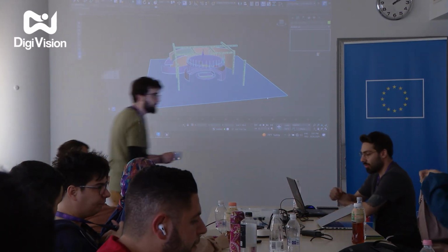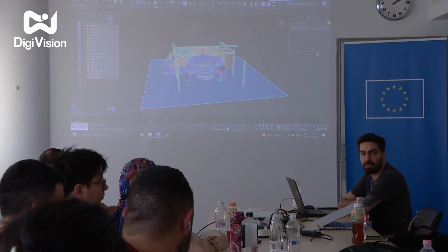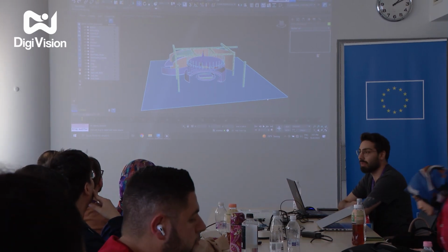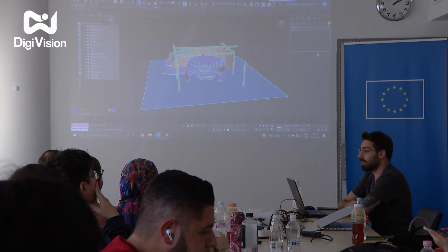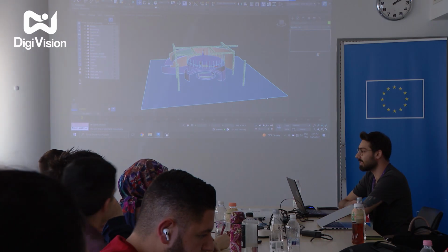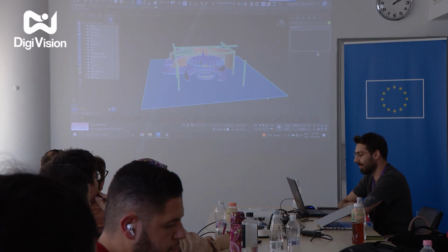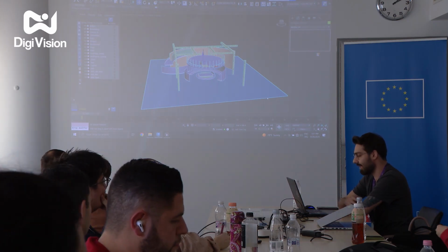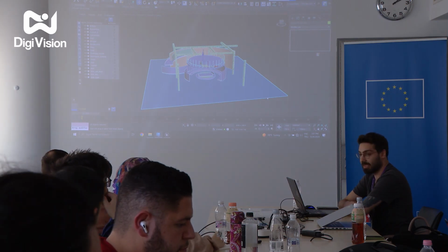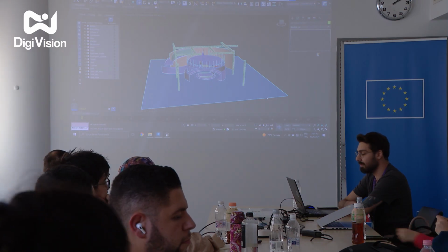So today we are going to use 3ds Max to export our 3D models, and we are going to import it into the Unreal Engine. After that, we will start to create some materials as base materials, and we will create some instance materials from the base materials, and we will just work on some lighting stuff to make it a little bit fancier, and maybe we can add some post-process volume to see how the color works in the scene.